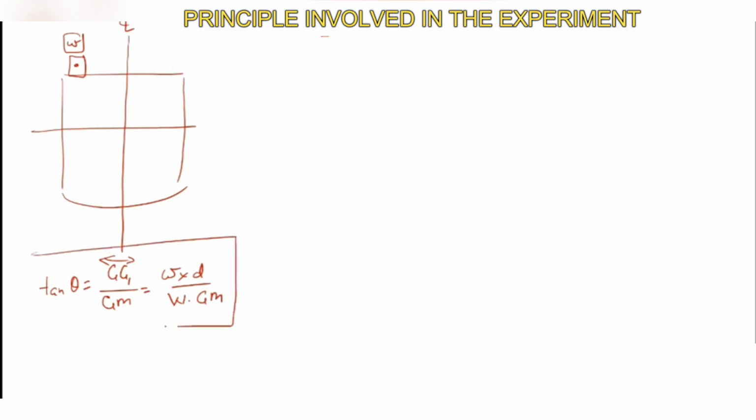Correct? Yes, sir. Which I know, then I know the w that I'm shifting. I know the distance through which it has been shifted. By taking the drafts of the ship, I can get the displacement of the vessel. And if I can measure exactly the list caused by shifting this w weight, if I can measure the theta, then what do I know in this expression?